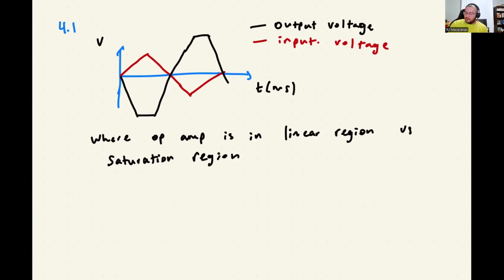One thing they have here is that the input is going up to about 2 volts, and the output, it's hard to tell here, but it looks like 3.3 volts up here. So clearly they've got a 3.3 volt supply. It's going down to minus 3.3 volts here.